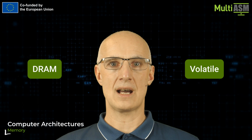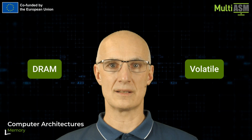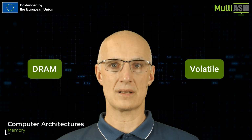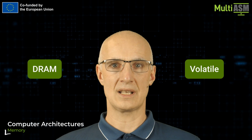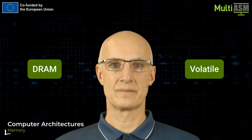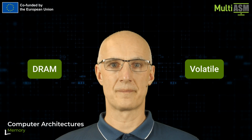The memory used as an operational memory in bigger computer systems is DRAM, Dynamic Random Access Memory. Its main benefit is very high density. Every bit is implemented as a single transistor and information is stored in a capacitor beneath it. It is possible to develop integrated circuits with a few gigabytes in a small area. Another benefit is the reduced power required to store the data in comparison to the static memory, but there are also drawbacks. DRAM memory is significantly slower than SRAM.